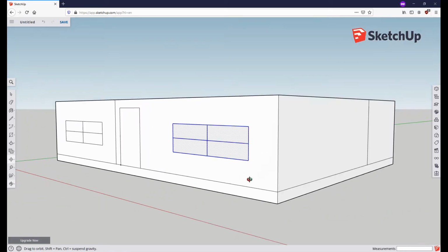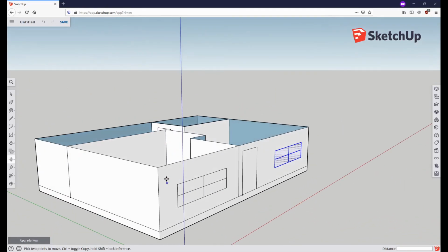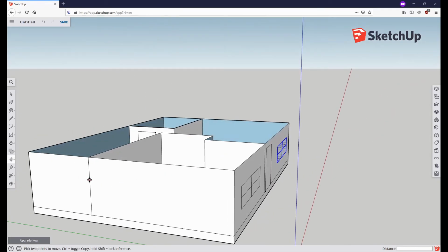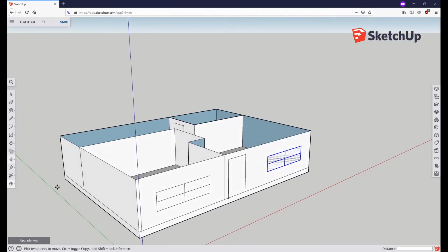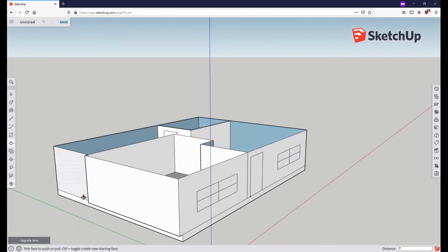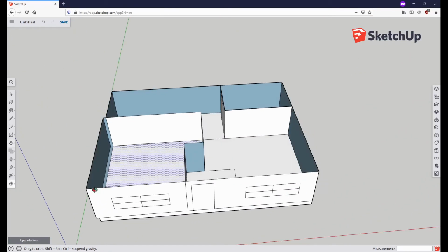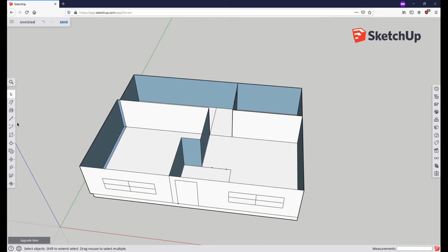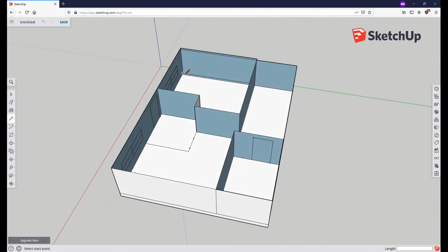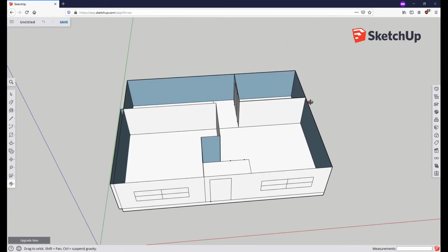Now you could use the measuring tool, or just create a line to snap it to and make sure it's even again, but I'm just going to show you here quickly what's possible. One thing to note is that our walls here have no depth, but walls in real life do. So we can use the push-pull tool to create some depth to our walls. And when you do create a project, you will eventually want to do that, just because it will matter. So here you can see it's created a separate space now, apart from the original, and that lets us use a line to snap the rest of it too. So now we have actual walls.